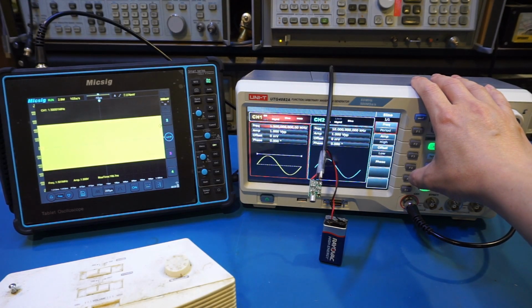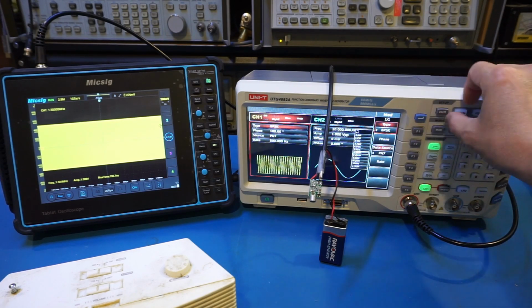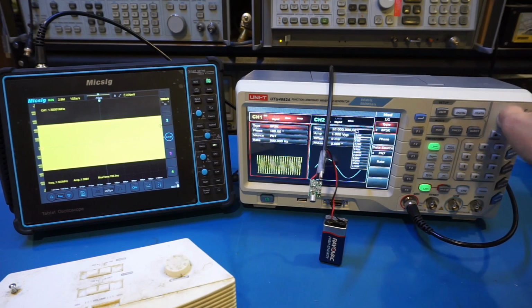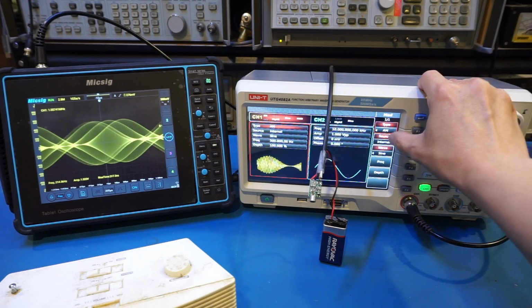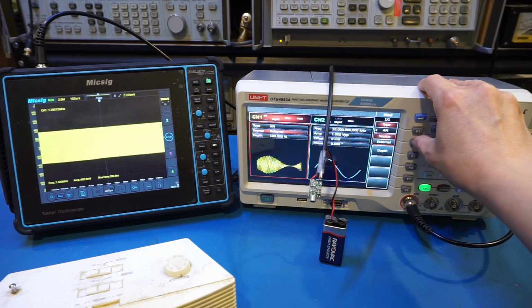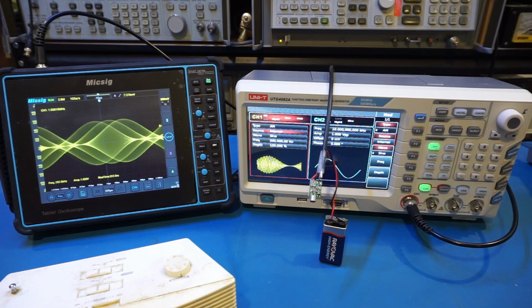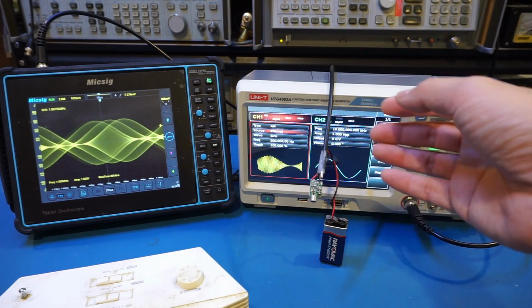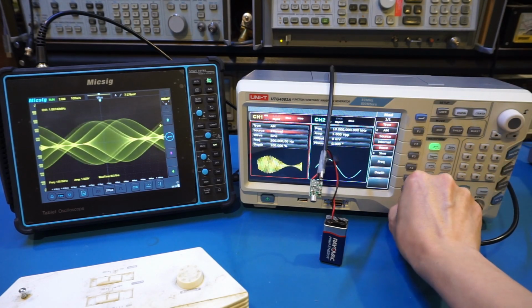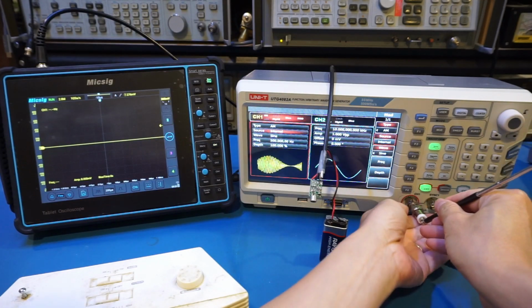And let's do the amplitude, we'll leave alone. Let's do the modulation here. So modulation, obviously we want to do AM. And that should be fine. The modulation source right now is internal. Let's do external. Actually, let's do internal first, because right now we're modulating with a 500 hertz signal, so we should be able to capture that on the radio here. And of course, for us to be able to receive through the radio, we have to add an antenna. So let me disconnect the BNC cable, and let me add in a whip antenna here, so we can try to see if we can capture that signal.